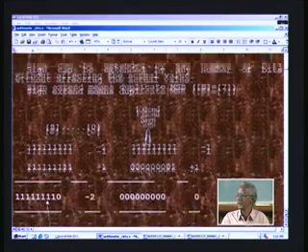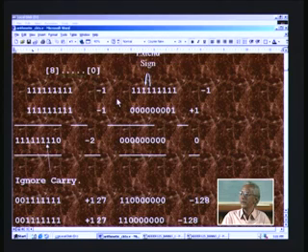So to illustrate with examples, let us consider -1, we will add 2 -1. So the result must be -2 in decimal, and when you add this here, it is simple addition here, 1 plus 1 is 0, and so on. So finally a carry will emerge, ignore that carry. If you drop the carry and interpret this straight away, you can easily interpret it as -2, because this is normal addition without regard to any sign, right.